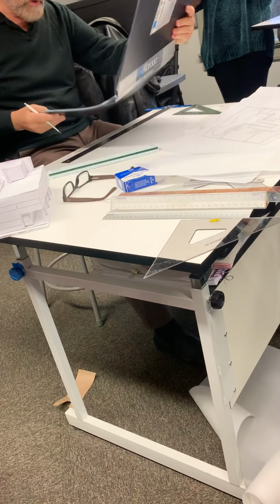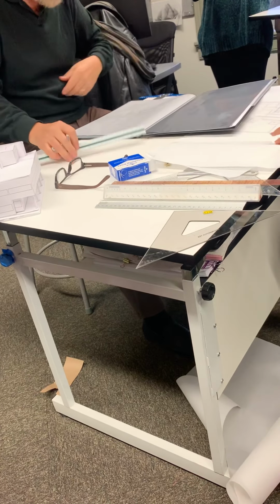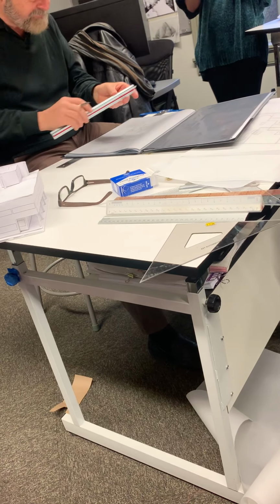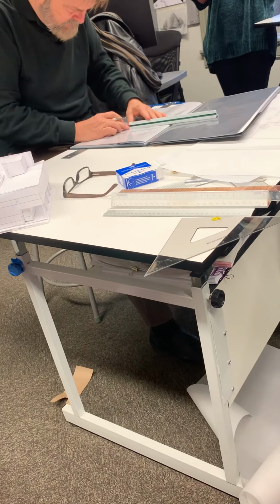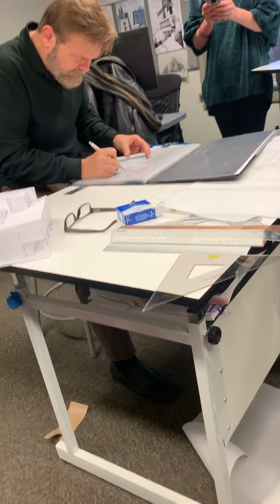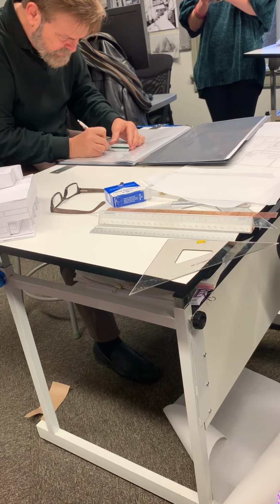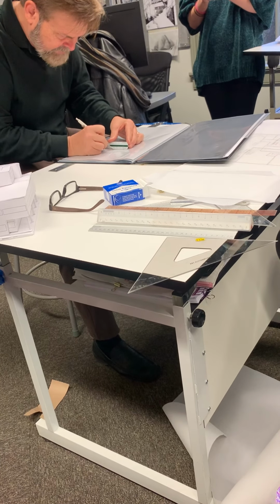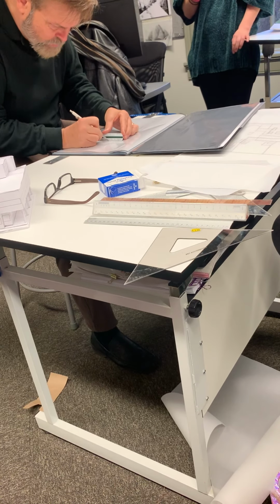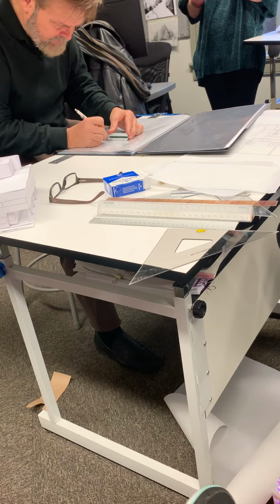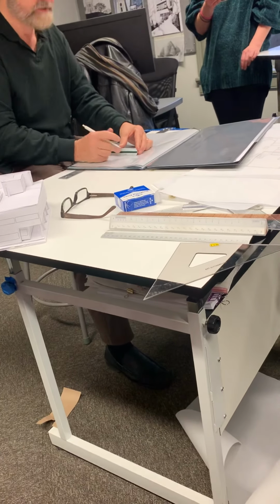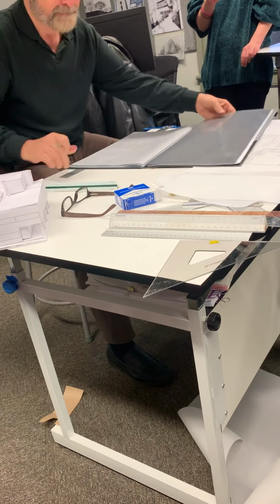All right, so here we have that. Now, we're looking here, we're going to be seeing basically at the top of the parapet, okay? And this is also done at 1/8 inch. So we're looking for the bottom here, which is the floor. So we're going to go to the top of this, and we said that was 12 and 6 inches. So I'm going to make that 12, and then we'll add the 6 inches on for the parapet. Okay, so that's 12 feet exactly.